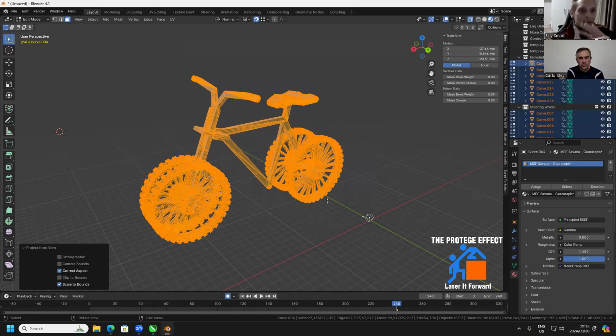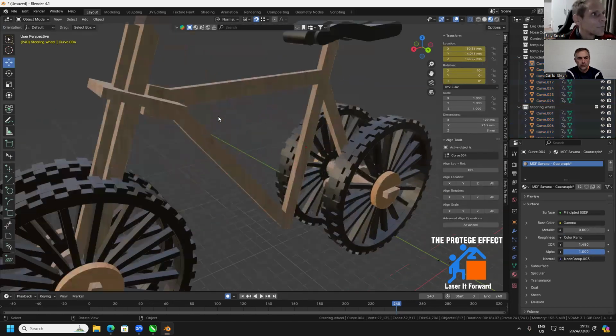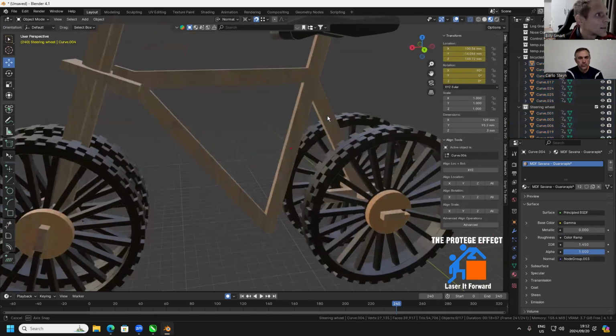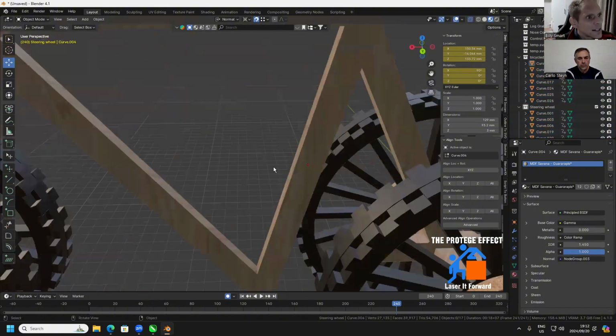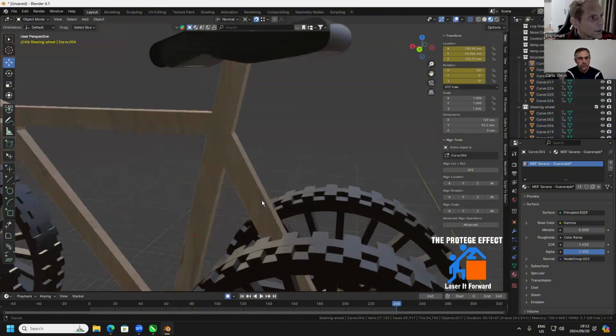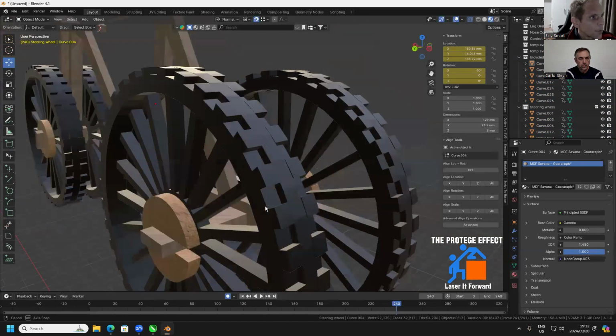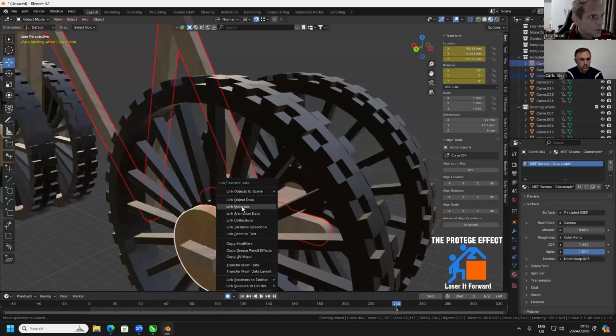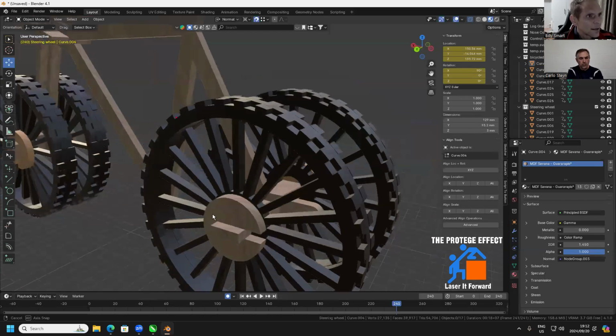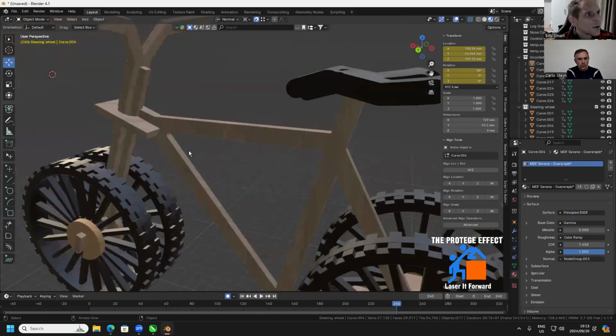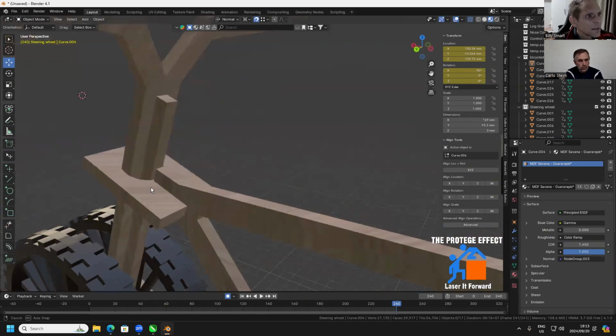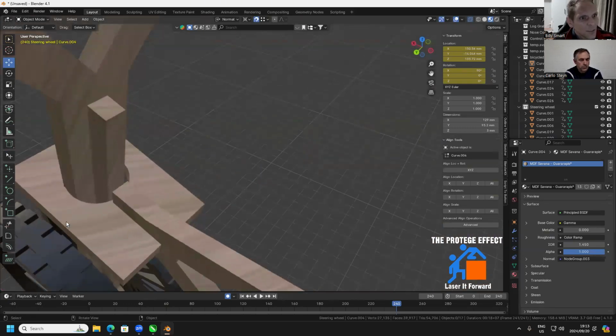Normally you could mix it up so that it actually looks like different pieces of wood, but I'll show you the effect. Yeah, it works. Link materials. There's 2 pieces that actually do go. Okay, here's a good place to see. So you see over here, because I said project from view, it projected the same texture over this piece and this piece. So it looks like it was cut from the same piece of wood, but in reality, it wouldn't actually be that.